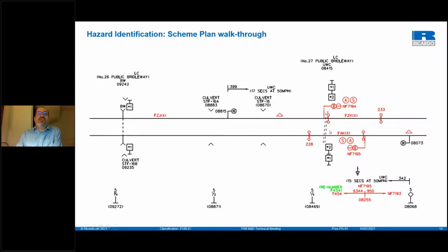So especially a person with restricted mobility might actually be in a position where the train could impinge on their passage across the crossing, which wouldn't be a very good thing. So this is an example of a new signal going in that might be compliant with standards, but I would suggest that it needs to be looked at and, if possible, moved further back, so that the crossing user has more warning of a train starting from a signal.